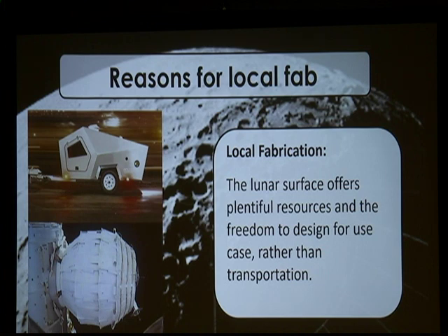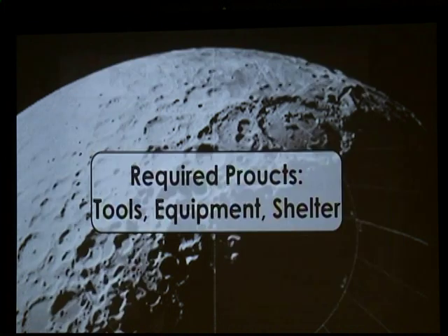And then down below, we've got the Bigelow inflatable habitat module that's on the ISS right now. Even an inflatable module that collapses down and doesn't have to support launch loads, like a trailer, just like a rigid module that's launched on a rocket, has to support those transportation loads. On the moon, we've got significantly lower gravity than Earth, but we also never see 3 times that on a launch if we never have to launch it. So we can build essentially weaker, but we can build to suit the use case rather than the transportation case, which almost invariably is better if you actually know what you're doing.